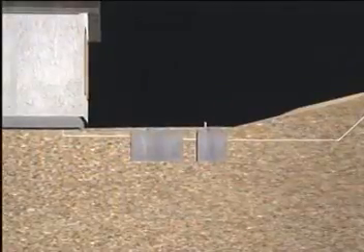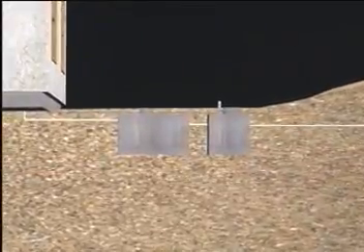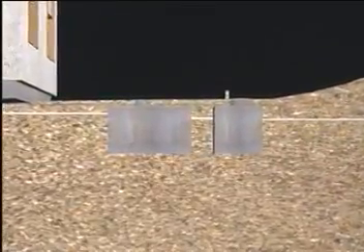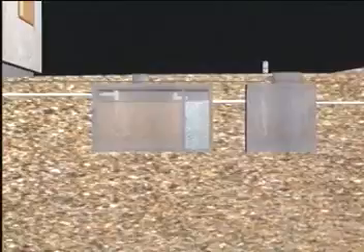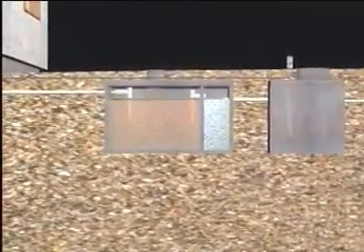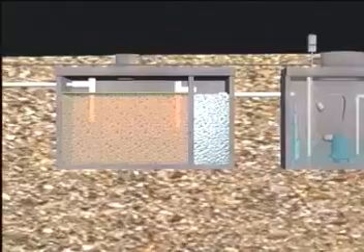Before choosing a basin or pump chamber, it's imperative you consult local plumbing and/or building codes. Basins and pump chambers, most commonly of concrete, polyethylene, fiberglass, or coated steel, are required to be leak-proof and watertight. Other considerations include buoyancy prevention, structural loading, and other characteristics based on installation locale and local codes.